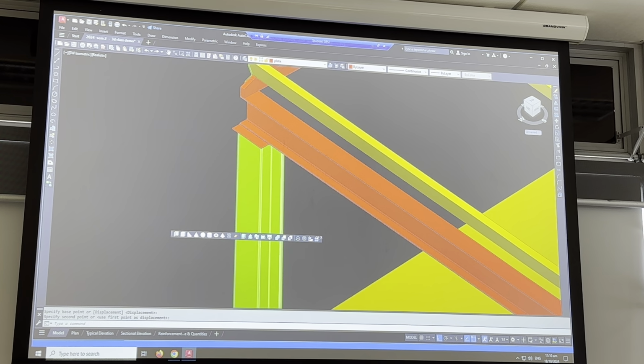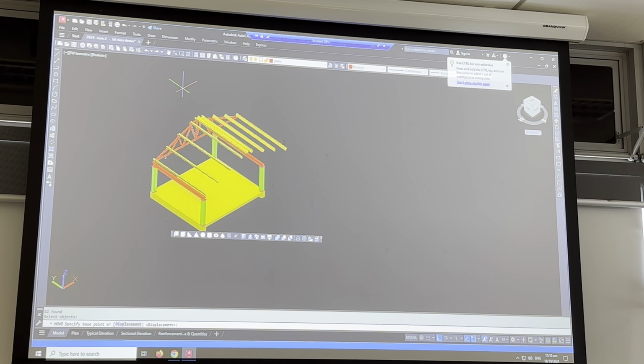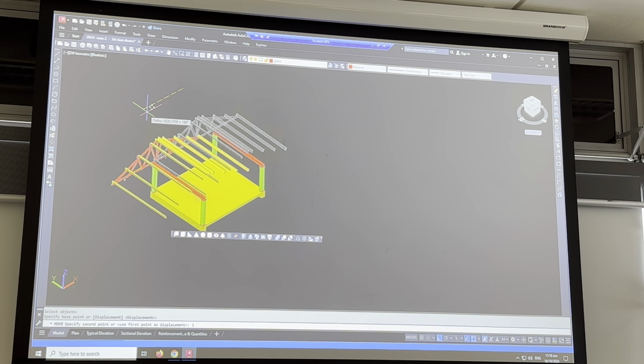But of course, we're now going to have to slide it, so that's where we have to do the maths. How much does that stick out? How much does that go past the edge of there? Does anybody have a dimension there? 1475. Let's hope that I can do this by going move, enter, P for previous. Yep. Enter 1470, sorry. 1470, enter. Here we are.